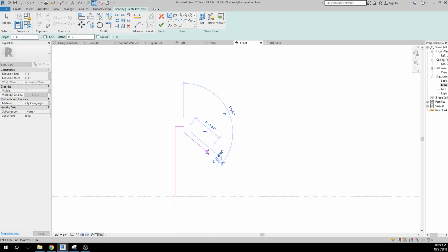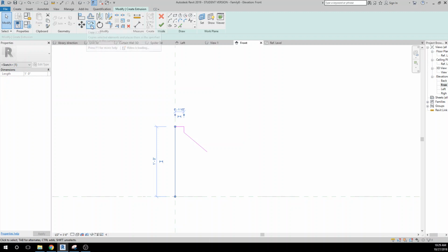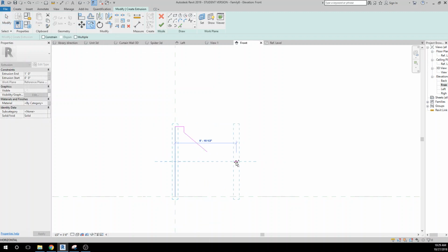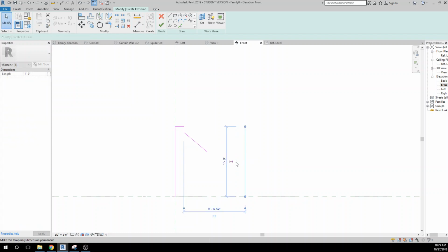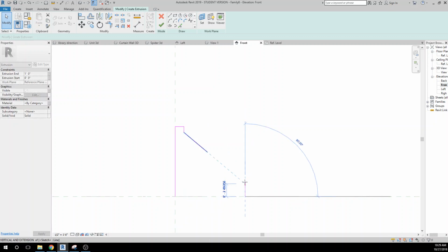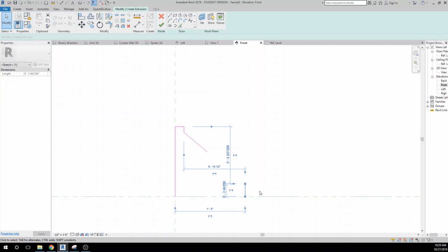And then we're going to move off this way, and I'll just click out and leave that for a moment, because what I'd like to do is set that other idea of this thing being out another foot this way. That's the very edge of that element. And I'll just bring this down just to make it more workable. So this is the very furthest extent coming out 1 foot. We'll actually let that be the center line of the pad that goes under here. And let's give this some sort of a depth. Let's see here. We'll make this 1 inch deep. Oops, I did that wrong.